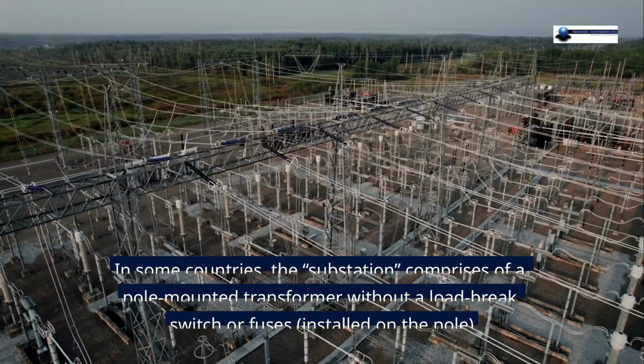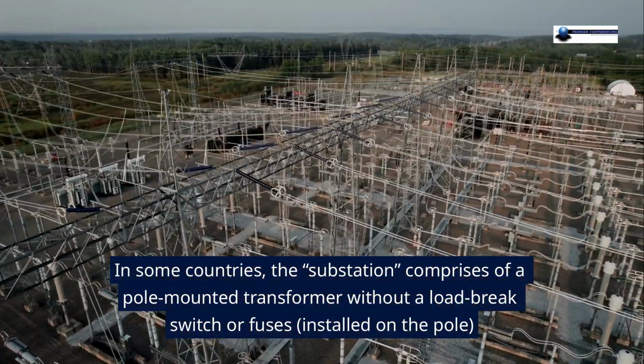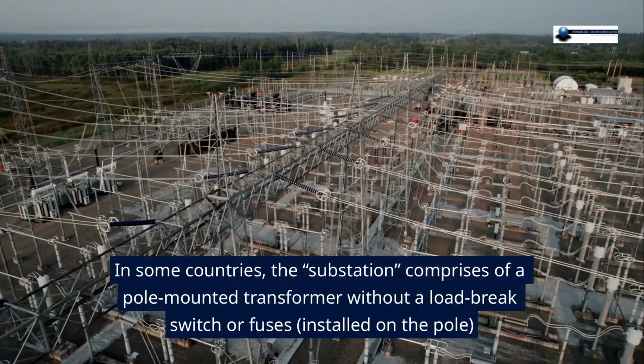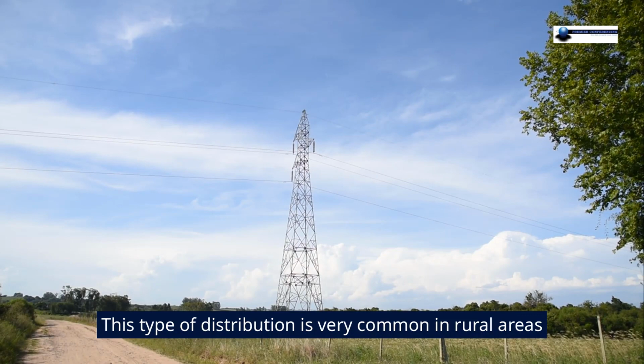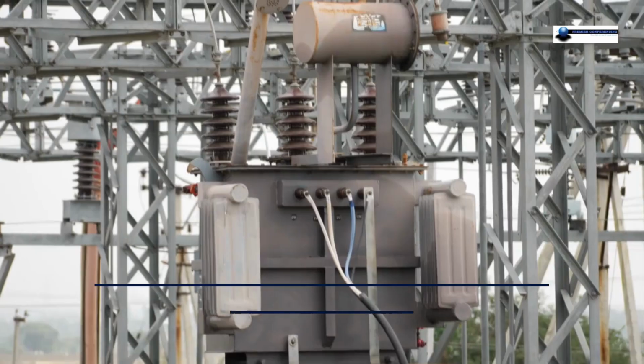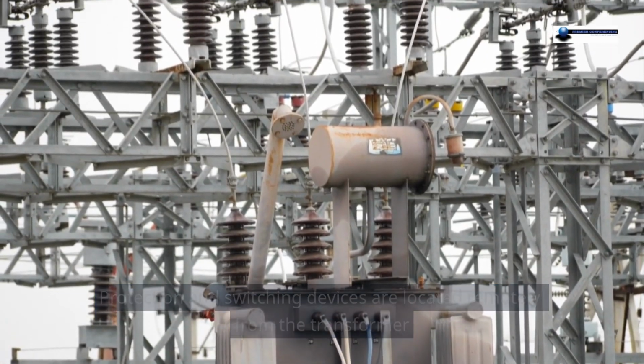In some countries, the substation comprises a pole-mounted transformer without a load break switch or fuses installed on the pole. This type of distribution is very common in rural areas. Protection and switching devices are located remotely from the transformer.